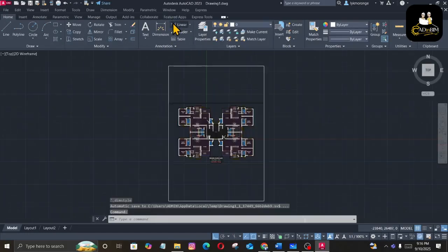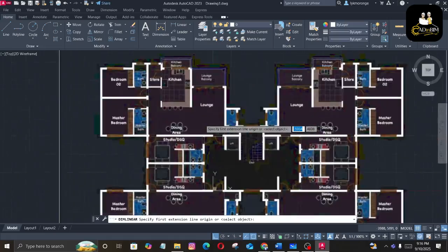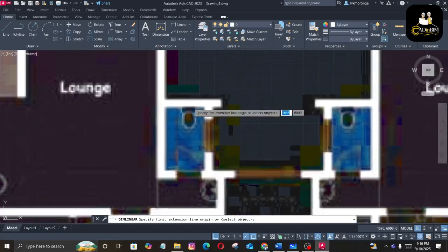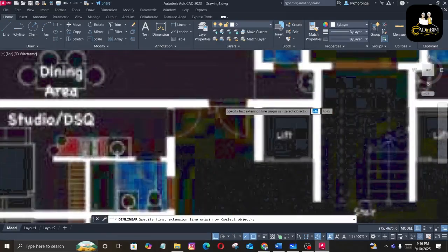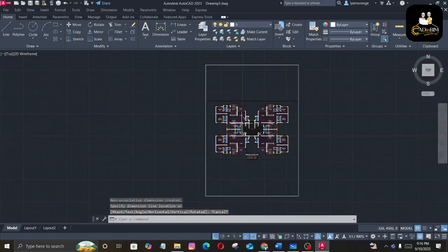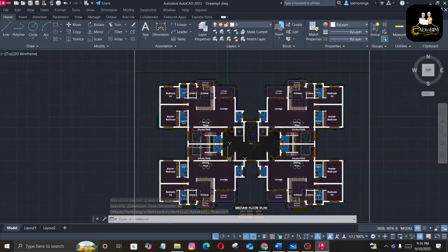So you can go to your measurement, and now you try to see whether you scaled your model correctly. I want to measure the door, and we see. Yes, you can see you have around 835, which is fairly okay. So once you do your units and you are scaling, the next thing you have to check is to do our layers before we start drawing.